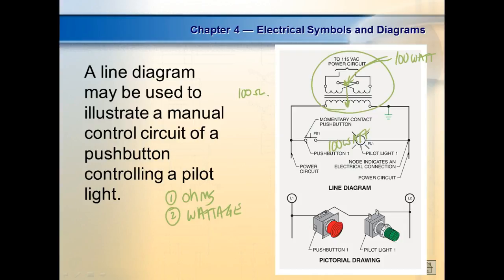Well, what was the problem? This is a 100 ohm resistor, and we were putting 30 volts on that thing. So that's going to be 30 squared divided by 100, right? You understand? So what's 30 squared? 900 divided by 100. So they needed a 9 watt resistor, and they were putting a 1/4 watt resistor in there and burning them up as fast as they put them in. All they were looking for was a 100 ohm resistor.